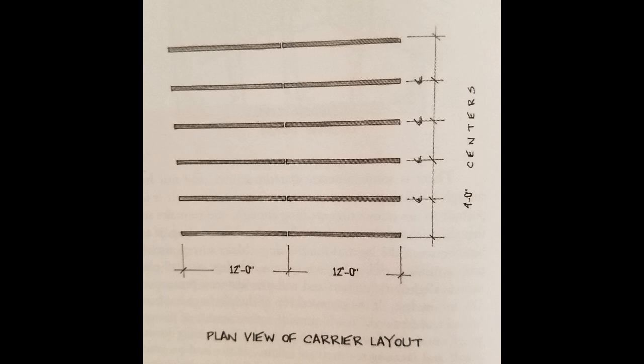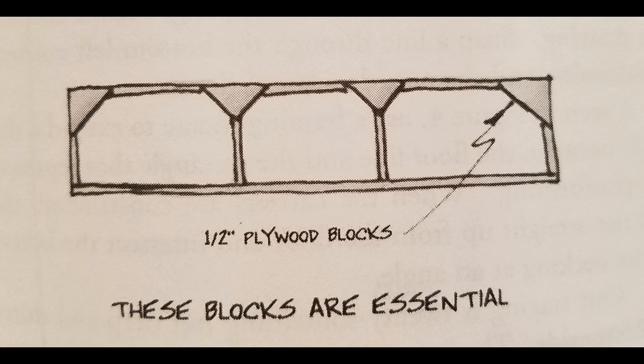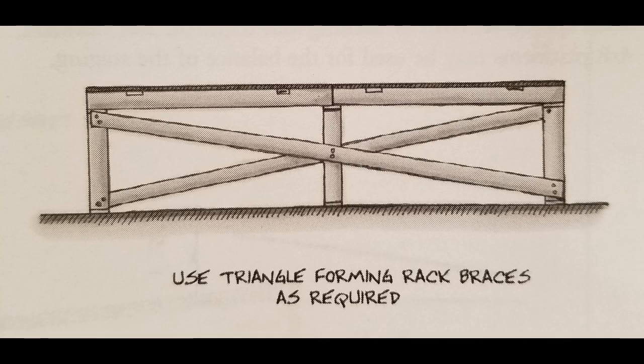Basic construction of the stud wall is very similar to the structures themselves of your stock pieces, but in this particular case, extra pieces of blocks are added, and they can be either out of half ply or 3/4 ply, depending on what is more readily available. And those basically help prevent the overall structure of that stud wall from crumbling under the weight of all of the platforms. You'll typically then want to use what is known as cross bracing. And this is where you can, again, still use 2x4, or you can go to 1x4 to create your cross bracing. Now, cross bracing basically allows you to attach multiple pieces, such as those stud walls, together, so they help maintain staying completely vertical and allow them to not shift around due to the actors or the scene happening on top of them.